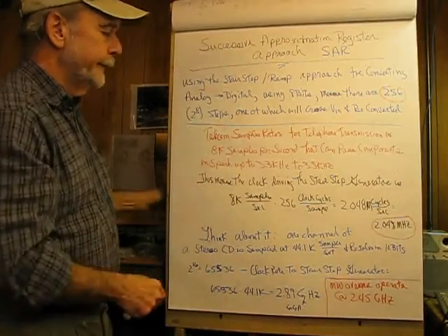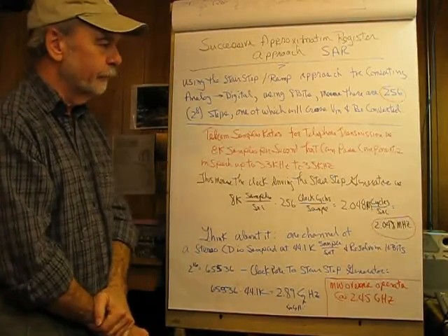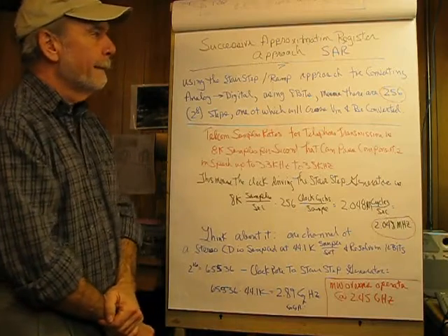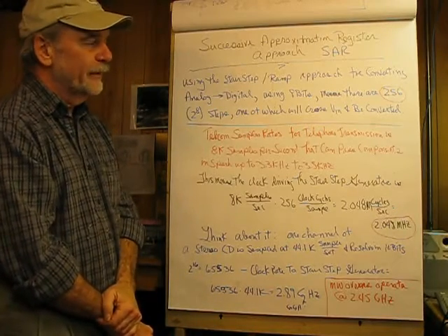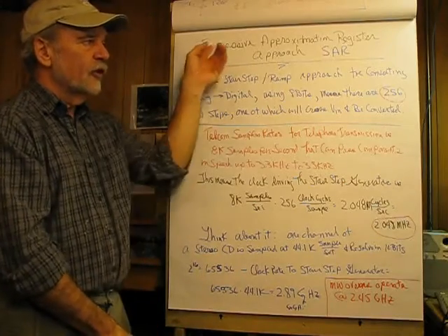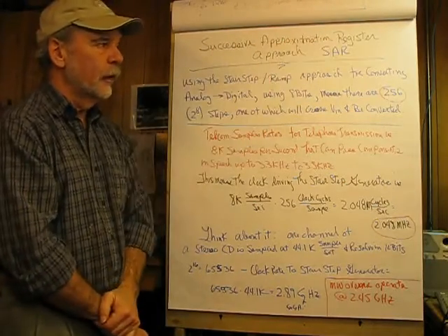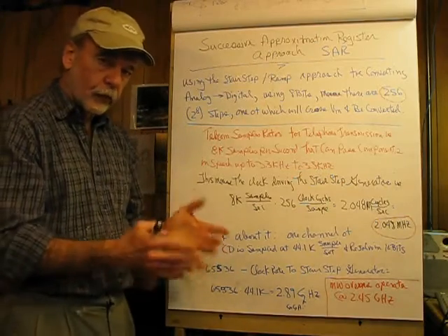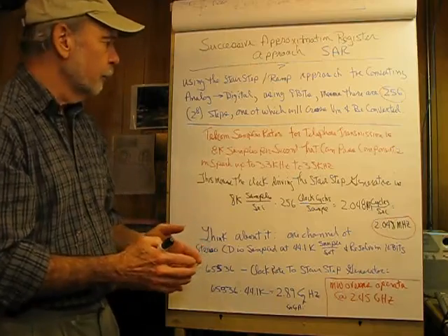Now, this is kind of a verbose way to do it with these up-counting steps. So the industry figured out a better way to do it, and that's using a successive approximation register, referred to as an SAR, a component that couples well with an R2R network.